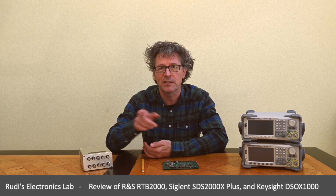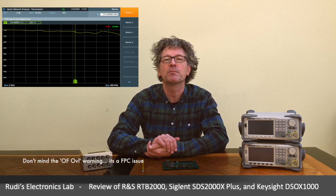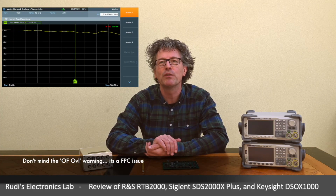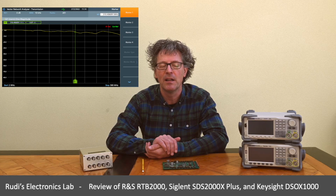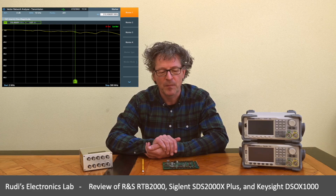Of course, I had to check whether that works well for the purpose. So I ran some tests on my spectrum analyzer, or rather the vector network analyzer, and did an S21 plot. What we see is that up to 300 megahertz, the splitter is perfectly fine. Everything is within 3 decibels of attenuation within that bandwidth. So that's perfectly fine for the type of things that I'm doing here. They're at max a couple of megahertz, so that's good.